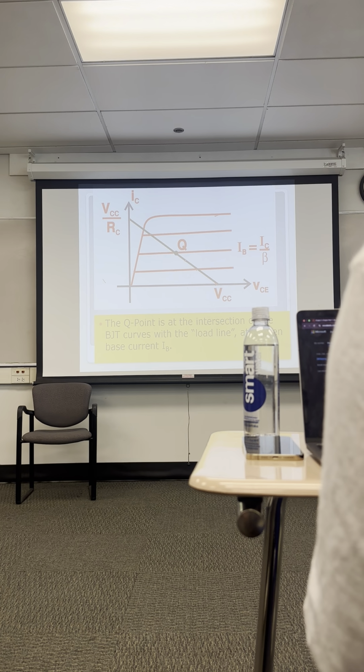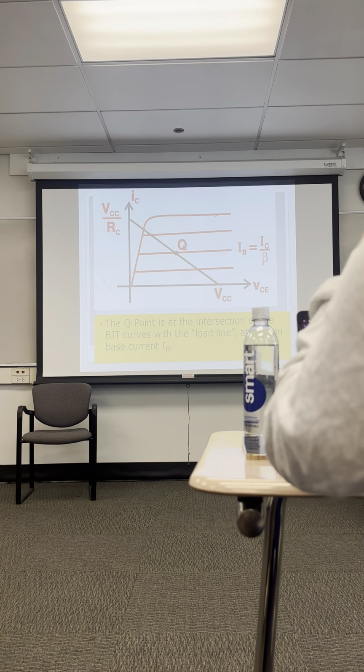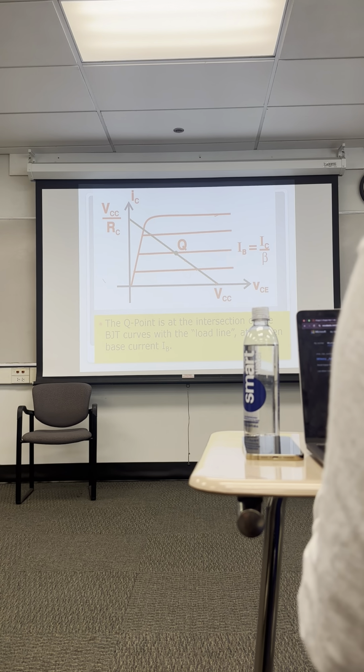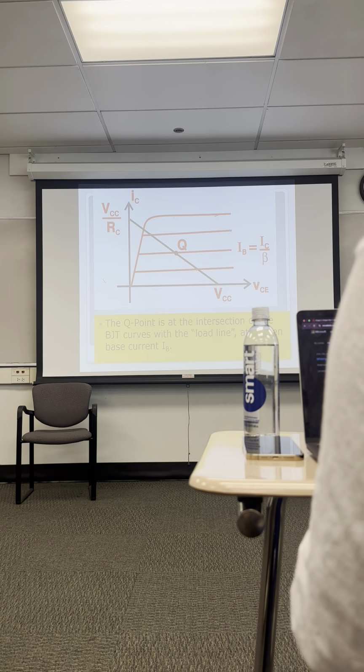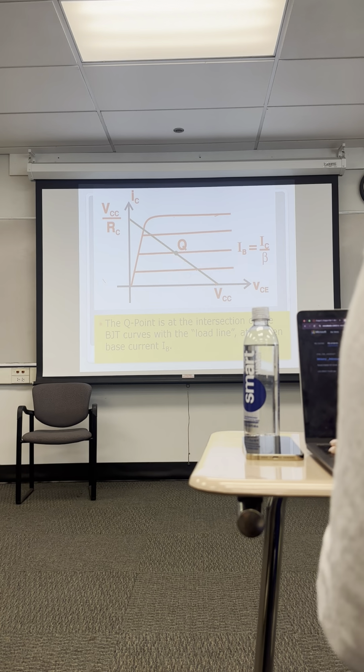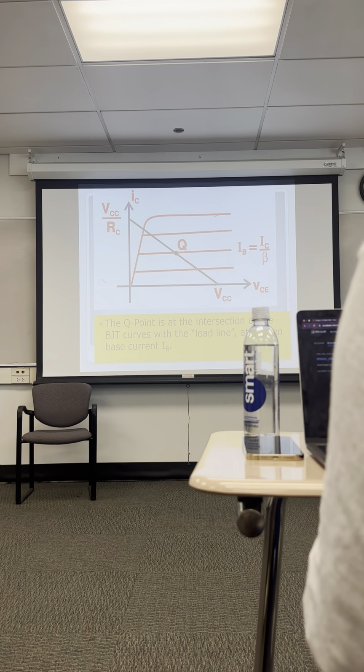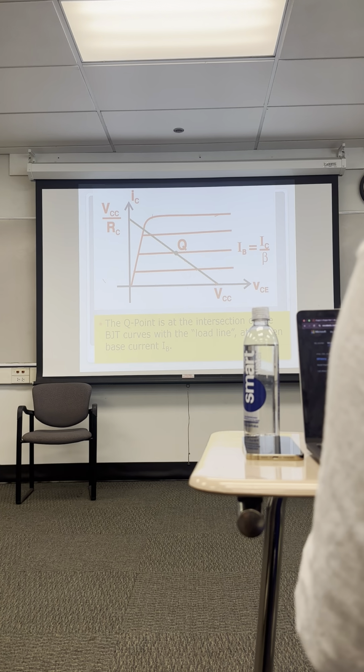So you can actually draw your own base currents in here. There are certain parts you stay away from. This lower curve is too close to cutoff, and this upper curve is too close to overdriving the amplifier and getting distortion. And then we also stay away from this V right here.